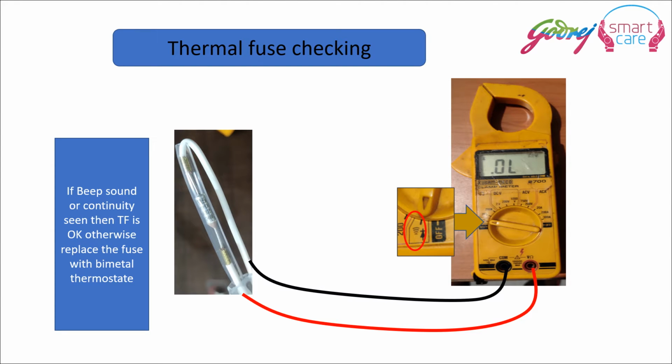Checking the thermal fuse is very easy. You have to check the continuity between the both ends of the thermal fuse, and it should show a continuity if the thermal fuse is intact, or it will show open if the thermal fuse is open.